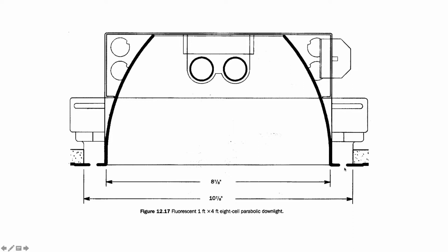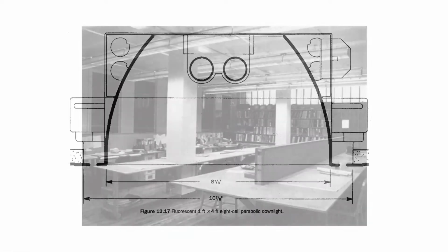You often use fluorescent troffers in conjunction with a plenum return. Plenum return is when the area above the ceiling acts as a giant dusty duct, and so the air can seep up through these corners of the light fixture and up into the plenum and then return back to the HVAC system. Not all luminaires work that way. At our art center, we have a ducted return. You can see it by the grill up in the ceiling.